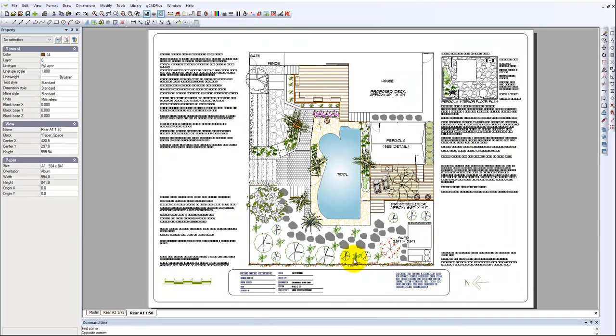So now we've matched the Australian design rule as far as the use of scales in technical drawings, and this being a technical landscape drawing, we've got the correct scale. But our designer and our client want to see this on an A2 sheet. And the quick, convenient way to do that is just save a PDF. And what we'll do then is take that PDF, open it up in Acrobat Reader, and print another version on an A2 sheet. Let me demonstrate.